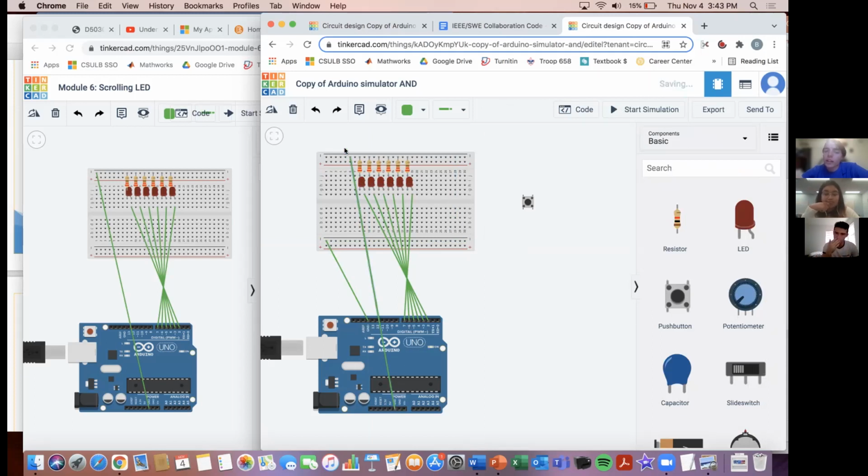Oh, okay. No, it doesn't matter. I can put it anywhere along this bus. I just can't connect it on this one because this one's not connected. You see how it makes the green here? See those green circles around each? That's where it applies. So it applies to all the resistors here. However, if I put it down here, it wouldn't apply to any of the resistors up there. It's not in that bus. So it's just along that line. It applies to all of them. So you could place it at the very right or the very left. It's still going to apply.